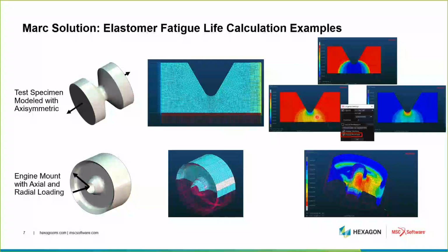We've implemented something else as well that is applicable definitely for fatigue, but could be applicable elsewhere. We've had similar requests for this, and that is to reverse the legend, to essentially make the colors that primarily you associate with the low values now associate with the high values and vice versa, as fatigue is one of those cases where the lower the life, the worse the case, and so generally people like to see that in the red. So we now have this legend reversed option, and you can use that for fatigue or other things. So that's a nice little addition that came with this.